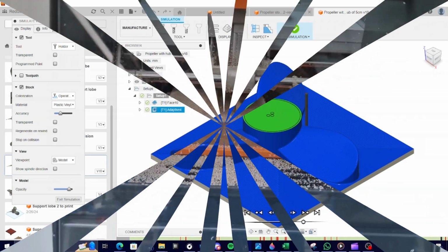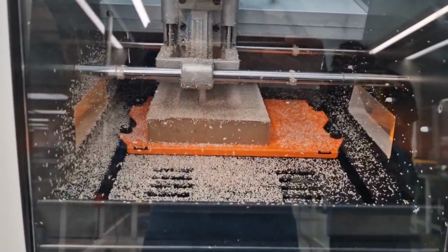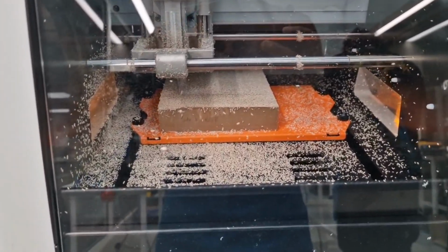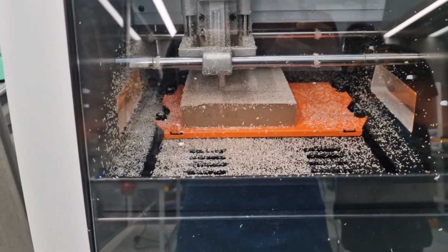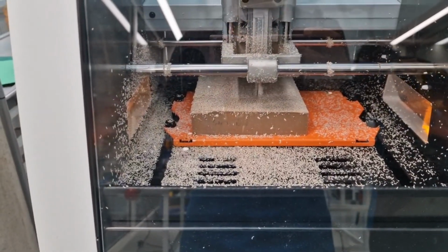When using the CNC machine, multiple issues were run into. The first major issue was due to the clamping of the stock down onto the CNC machine bed. The first approach was to simply make use of double-sided tape. This method proved effective at first, but it was then dependent on the size of the stock being used and